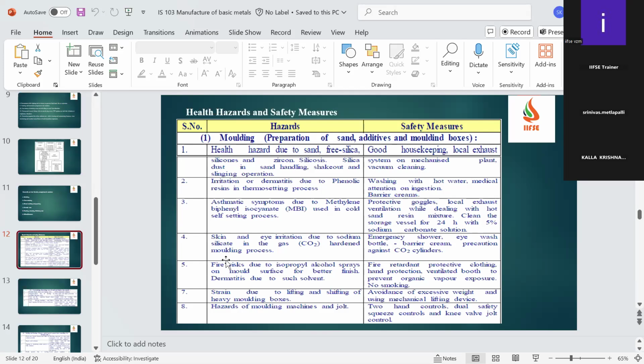Once the mold is ready, we will take out the pattern so that we can see how my job looks like. Then they will apply a coating. Then they will apply heat so that it will get hardened. So in the sense, it will become hardened so that the sand will not mix with the molten metal. It means the sand inclusion will not be there in the material.